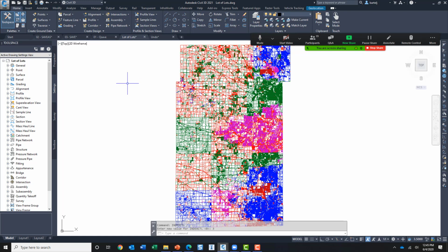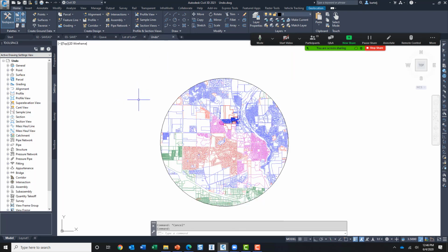Okay. Now, I'm not going to go through and reload it. It didn't take long to load anyway. I'm sure you have many examples with surfaces and other things like that you can test to confirm what I'm saying. But one thing I want to make sure you walk away with is I don't want you to think that I'll just set indexctl to 3 in every single file that I have, because I may or may not X-reference it in the future.